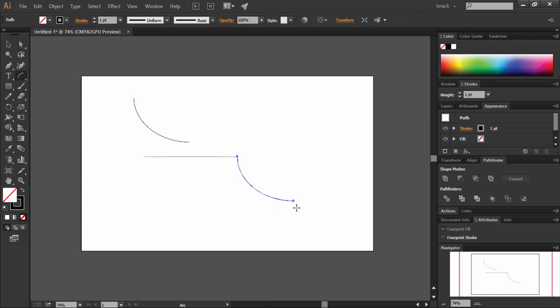Notice that I am not traveling up to the tools panel to select the black arrow tool. I will simply press the Control key to activate the black arrow tool, and I'll keep it pressed until I want to use this black arrow. We discussed this topic of shifting to the selection tool in a very previous lesson. So as I activated the black arrow, you have the bounding box making the originating point the upper left corner point of the bounding box.